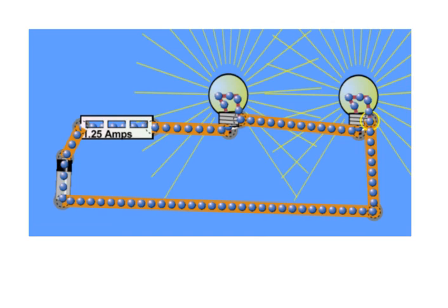Some of the electrons right here have to get used to make electricity, and so do some of them right here. And you'll notice that the amps right now has got cut in half. Right? There's not as much amps running through this thing, and so both light bulbs are now dimmer. This is one of the downsides to maybe doing a lazy job at building something in series. The other problem is if this light bulb here burns out, they both die.